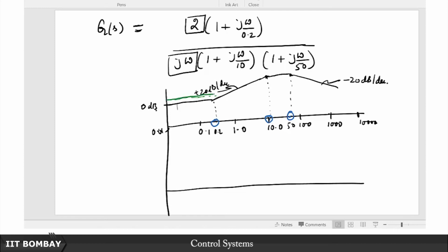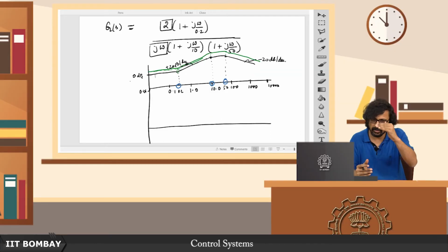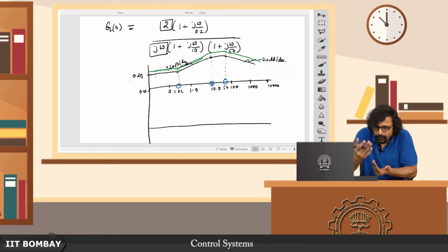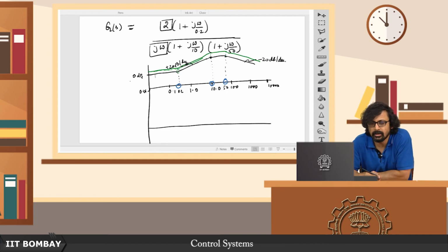So you can just say, now I am going to just retrace the same plot. Sorry, this does not look good. So let us retrace the same plot here, just a parallel line at every segment, you draw a line parallel like this and raise it here, and the same plot, okay. Or I could have been lazy and just relabel this 0 dB as 6 dB, I can just shift it. Either way, you either bring the axis down or you lift the plot. It's really not any difference, it's just relative, right.